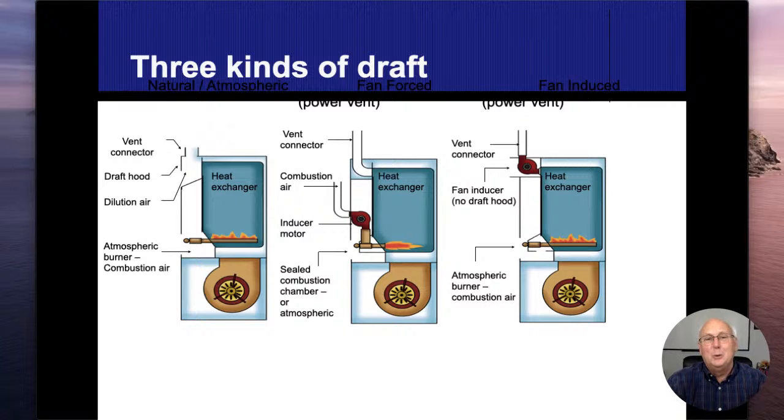All right. So we're really not going to run into too many furnaces that are forced draft. That's going to be on the very early stages of the higher efficiency furnaces. They realized this was a mistake. They realized that this was dangerous. As soon as those heat exchangers failed, then that carbon monoxide was going into the rooms and people could definitely get injured, killed, or whatever. It gets bad. All right. So we don't do that anymore.